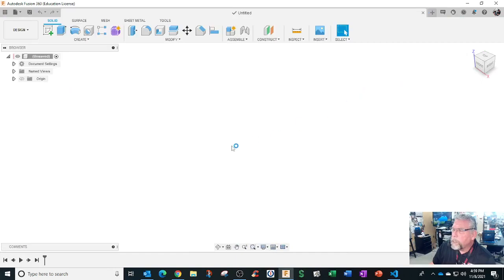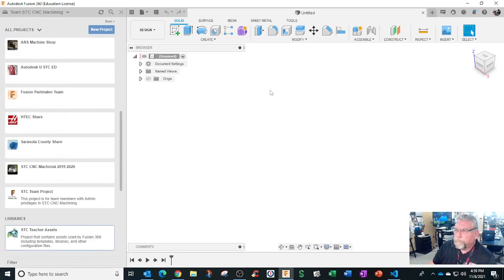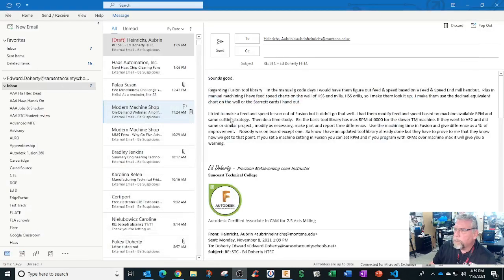As far as the feed and speed challenge thing, that's what I called it, the feed and speed challenge. I had them do the first one with the basic 6,000 RPM library, which was more RPM and feed than what Titan was telling you in the lesson plan, because he was using 4,000 and just 25 inches.